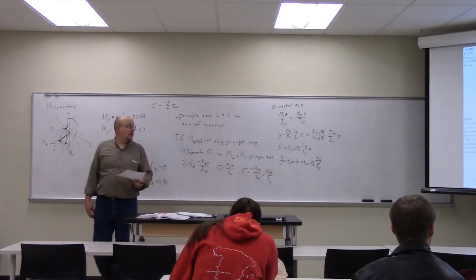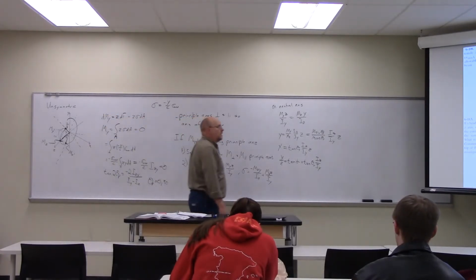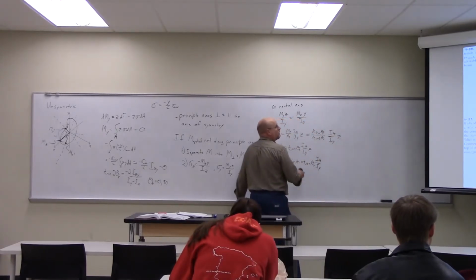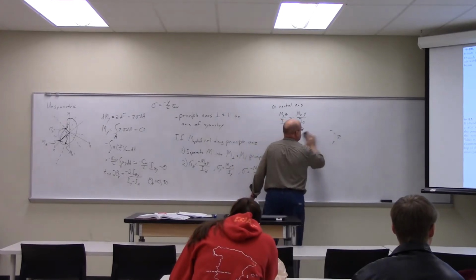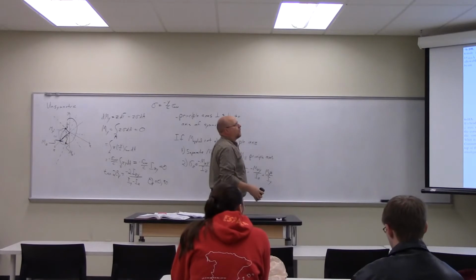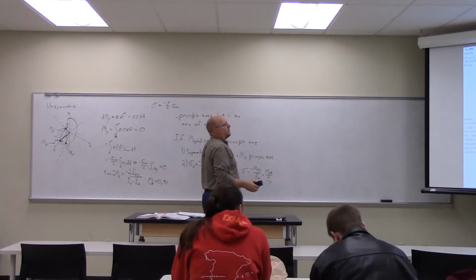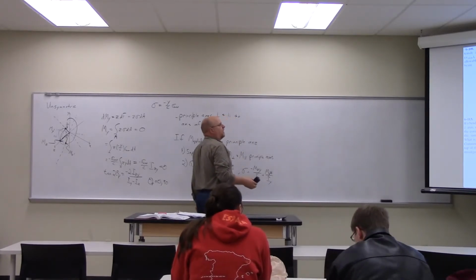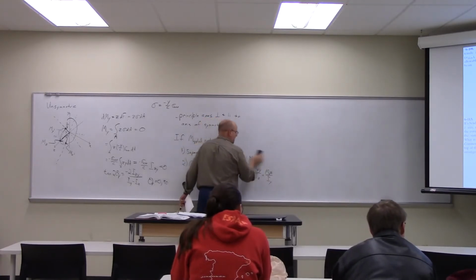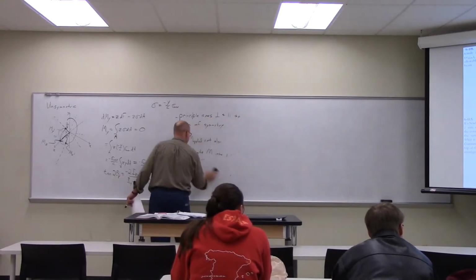All right. Let's do 6108. If the wood used for the T-beam has an allowable tensile and compressive stress, as shown, 4 and 6 megapascals respectively, determine the maximum allowable internal moment that can be applied to the beam. And they've given us a direction for the moment.